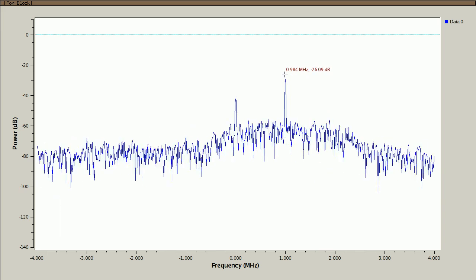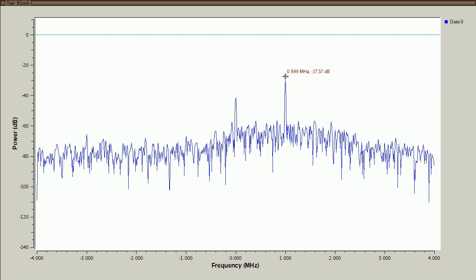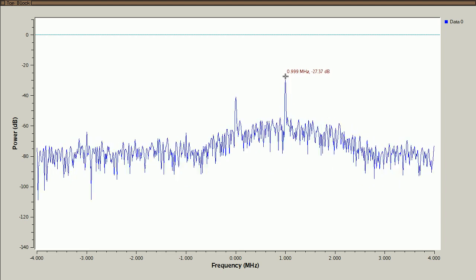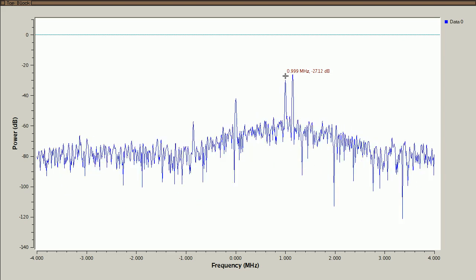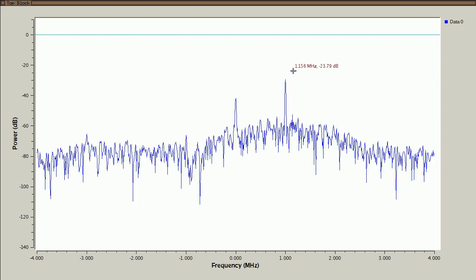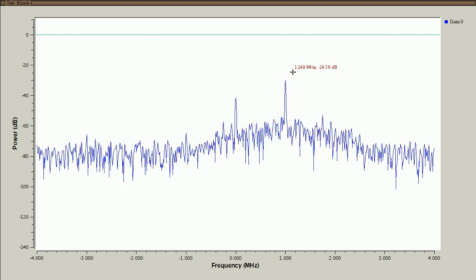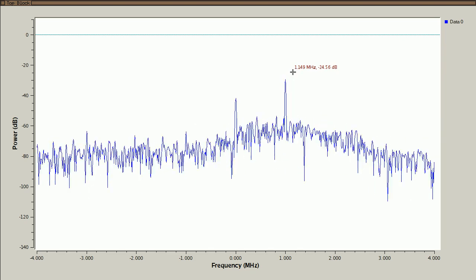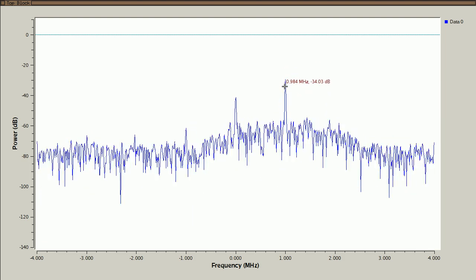That's actually the DC offset that was received by the first HackRF in the first place, and now we're retransmitting that spike. That's not very good, is it? This signal up here, 150 kilohertz higher, is actually the signal that we're intending to transmit. And then this spike 150 kilohertz below it is something that we shouldn't really be transmitting.